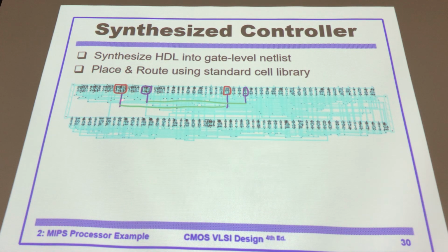The vertical is the purple color, the horizontal line is green color, and this is the contact. So these two wires do not touch each other, right? They just simply cross. That's why you need at least two metal layers.